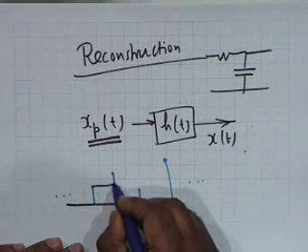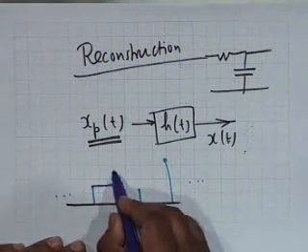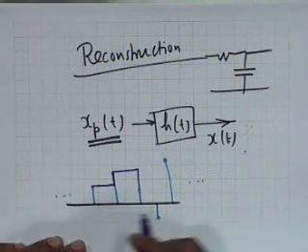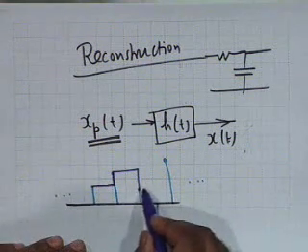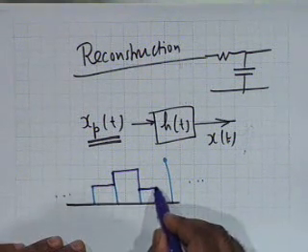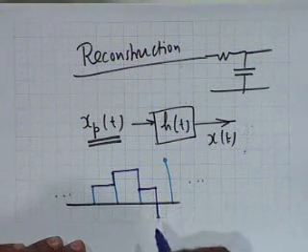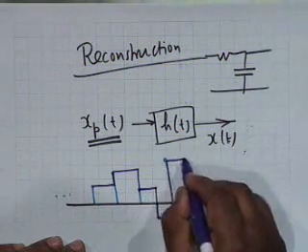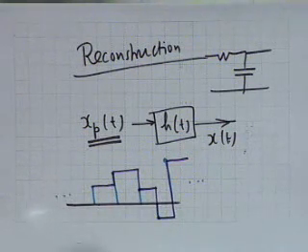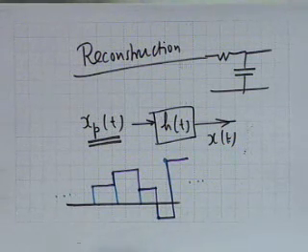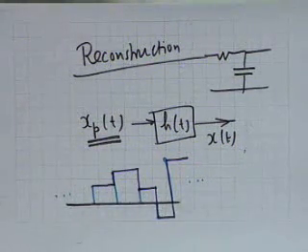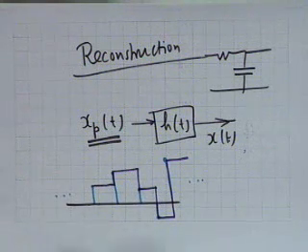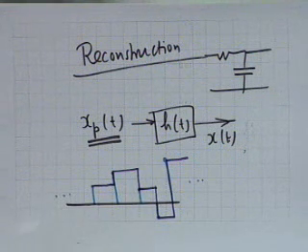When the next sample comes, the capacitor rises in voltage, then it remains constant up to the next sample, then it loses charge so that it reaches this level, then this level remains constant till the next sample comes, the charge becomes negative, and then this remains constant till the next one, and it goes up like this, then it remains constant, and so on. We can apply it to a zero order hold, and then to this zigzag version we can apply a low pass filter and have a recovery of the original signal to a reasonable degree of accuracy.